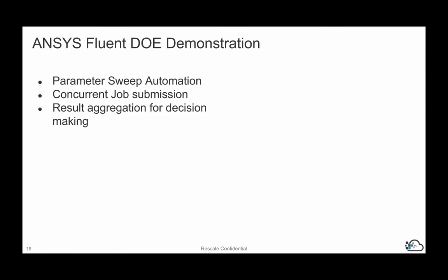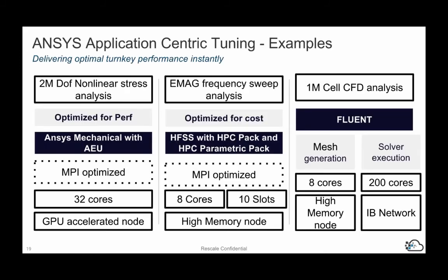And you also saw how we can automate some of the tasks using a post-processing script and extract some of those key values and display them in one single table, so you can review your results in one single place. We've also seen the chart capabilities that allow you to compare the different configurations and make a better design decision essentially.